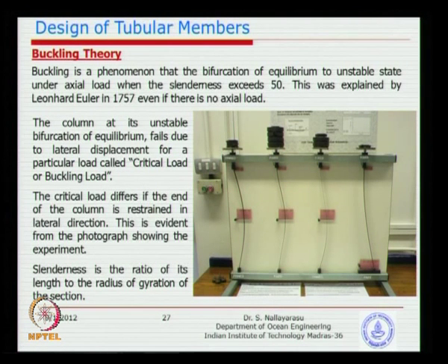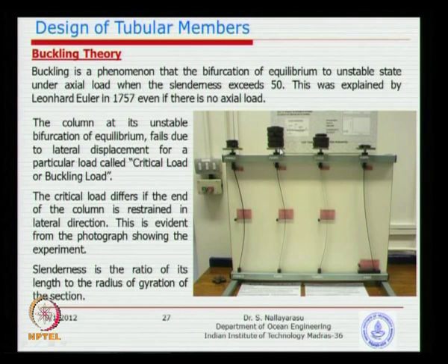So that means the effective length is the reflection of the load carrying capacity depending on the boundary conditions. You see here, one might be taking 4 times the load, whereas the other one carries only 1/4. So vice versa, we express the capability of the columns in terms of effective length, because one carries higher load and the other one carries lesser load.